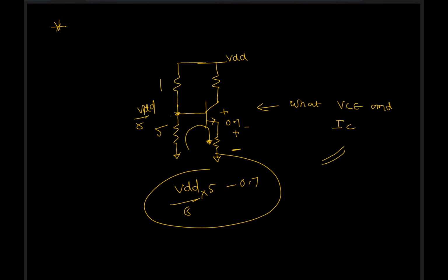So you can calculate the current as well as the VC, as this current will be approximately the same. In the questions you don't have to add the base current, that will be approximately the same, and if it is MCQ you can eliminate the options and check. So the tip is, consider IC is equal to IE, don't add the base current also.